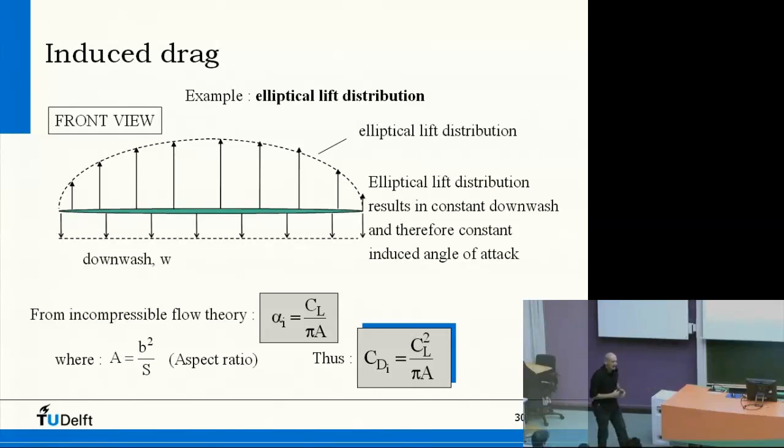And that's why I showed you the pictures in the beginning of the aircraft. They have an elliptical wing. Because lift, the force, is not only CL, it's also chord, because of surface. So if you play around with the chord, then you can also do something with the lift vector, with the lift force.